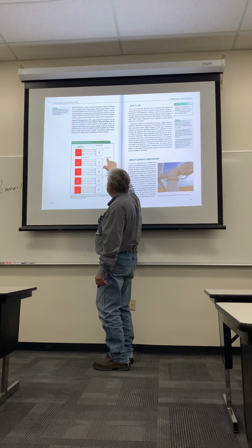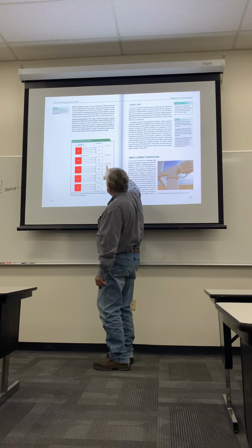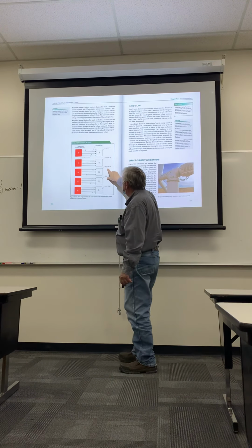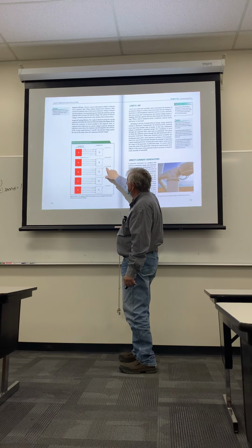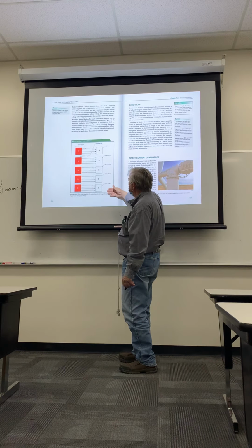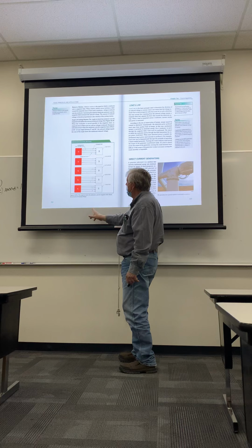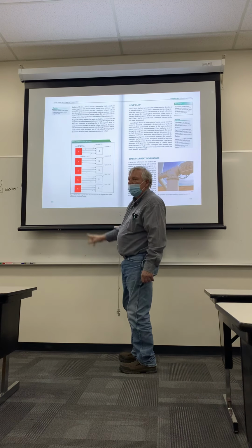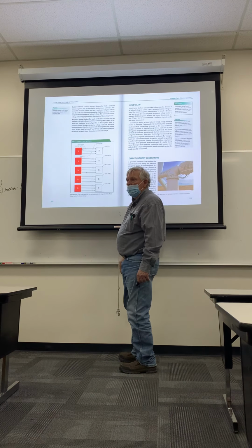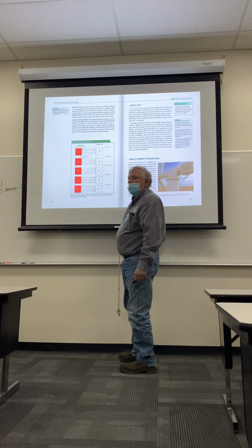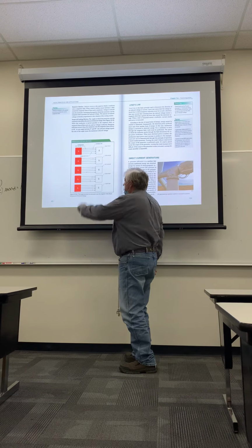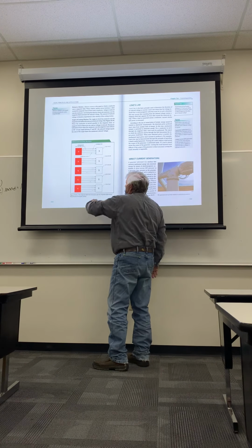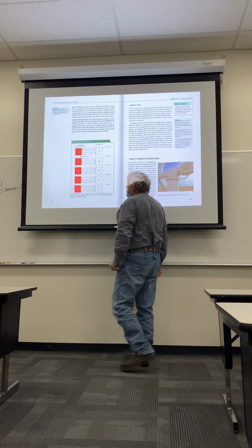in this particular magnet. If I increase that angle more, now we're at 45 degrees, we've increased to 0.7 volts. And I think you can see as you increase that to 90 degrees, or perpendicular to the lines of flux, so it's best to go straight across, that's where you're going to get the maximum amount of voltage. So you pass this conductor through these lines of flux, you end up with a volt at 90 degrees.